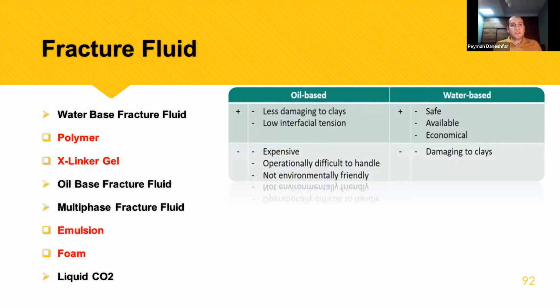The advantages of the oil base are low damage to clays and low interfacial tension; the disadvantages are that it is expensive, difficult to handle, and not environmentally friendly. For water base, it is safe, available, and economical, but damaging to the clays, and we should use some additive to control the clay.